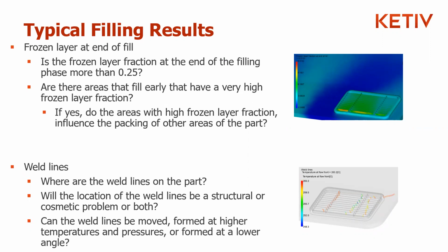Yep, absolutely. And that's one of the things that I absolutely love, overlaying results. So particularly with the weld lines, you can overlay that with the temperature. You can overlay that with just the fill time even, and that's one of my favorites. Yeah, every one of those overlays is going to give you varying degrees, varying types of information, which I think is great.